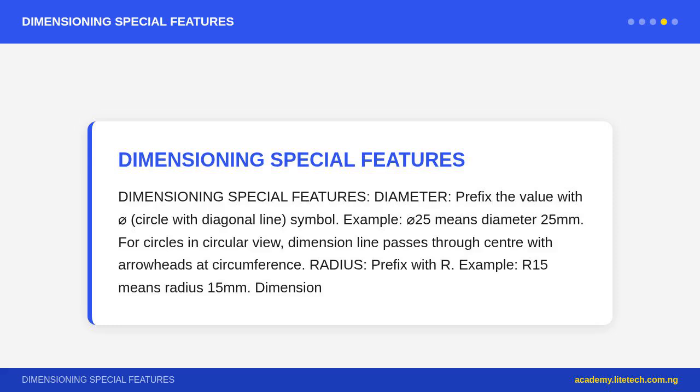WAEC Technical Drawing Questions on Lettering and Dimensioning. Question 1. State 4 rules that must be followed when dimensioning a technical drawing. Answer. Any 4 of: 1. Show every dimension needed for manufacture, none may be omitted. 2. Each dimension should appear only once, no duplication.